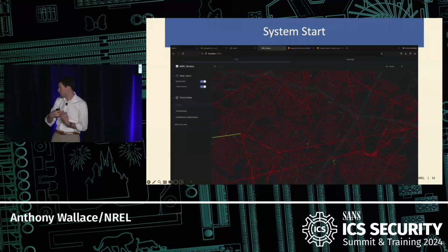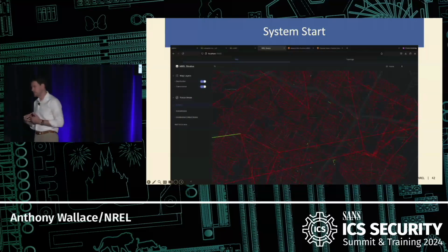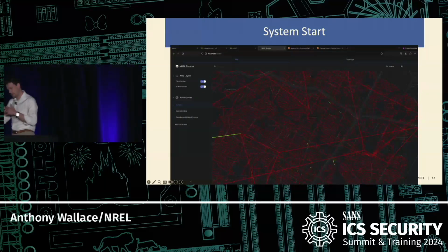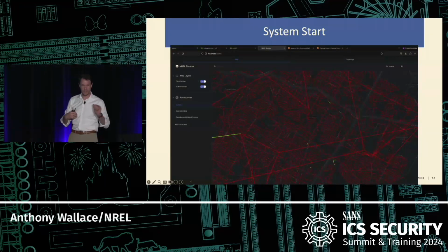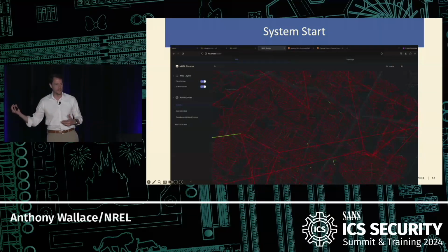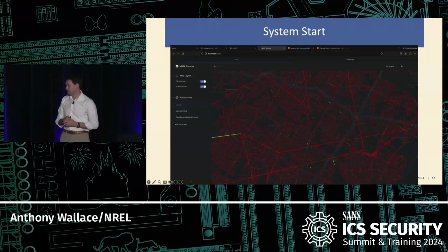We actually have points of common coupling for your utility guys in here between the distro and the transmission. So if you poke the distro, meaning if you shut down or open a breaker inside of a substation, you will see that reflected inside of the transmission via PowerWorld. This is all cobbled together with some Python scripts. We're trying to improve efficiency there. But for right now, it's a minimum viable product, and it allows us to answer some experimental questions.